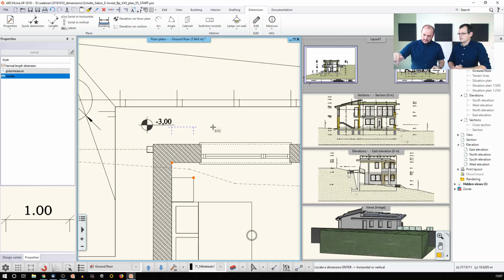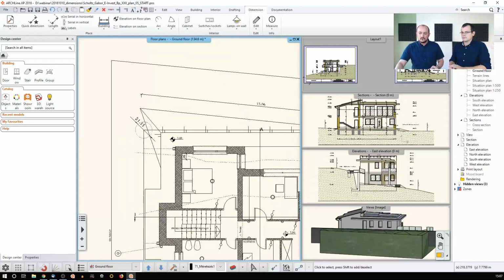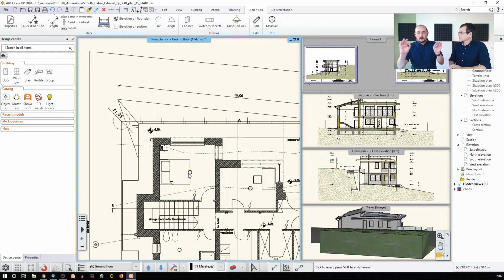If I right click again, it switches to the vertical component, and then I just click here and the software places that measurement. Whichever component I like, I move it someplace, click, and continue adding more and more dimensions. This is the simplest and most primitive tool if you would like to pick up 2 random points and measure their distance anywhere in your drawing.